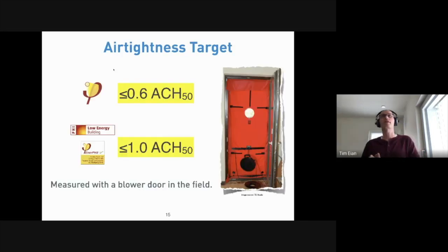Airtightness is another target. This one is not measured per square foot a year. It's a simple ACH 50 or CFM 50. There's some debate in the passive house community over using other targets and looking more at mapping the imperfections onto the envelope. And the PHIUS program, which is an American variant here, looks at it differently. But this is how the international standard does it still. So ACH 50. This works for small scale, medium scale residential or other small office buildings and things like that.